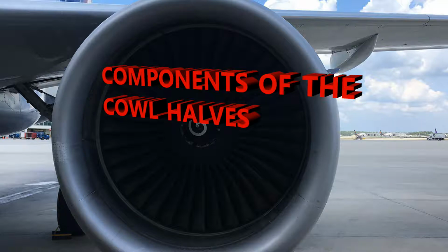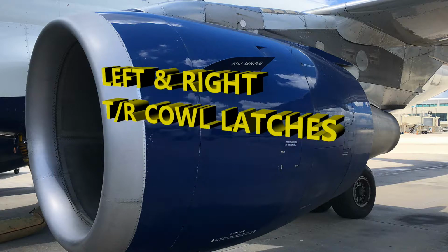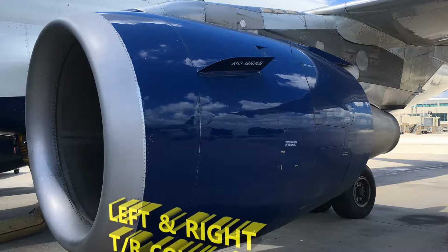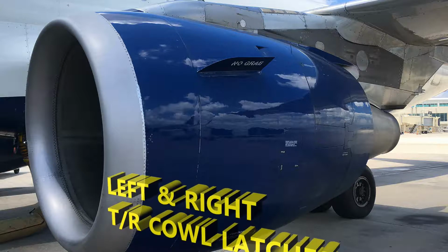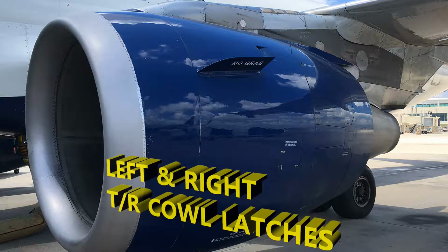All right, now let's talk first about the left thrust reverser cowl latches, and then I'm going to move to the right thrust reverser cowl latches. Be aware they're not all the same. Some of them are different types of latches. They're numbered, so follow the sequence in your maintenance manual. It's very key. Also, there's a lot to rigging because you want to make sure everything's aligned properly. There are again protective devices in there to make sure everything's good.